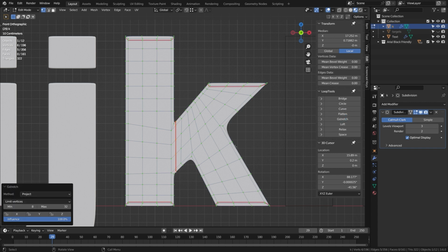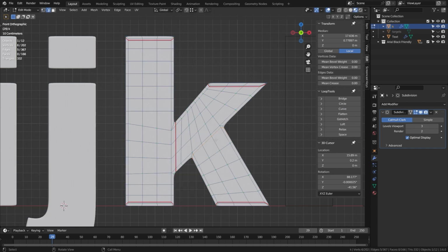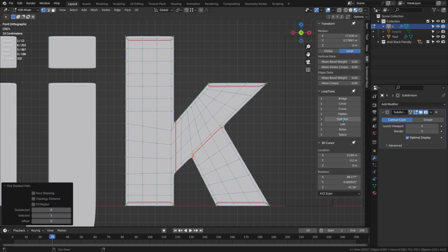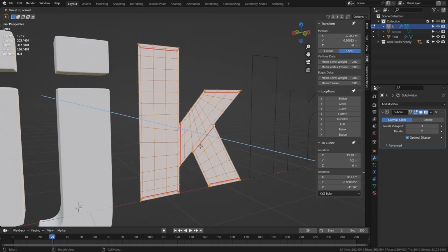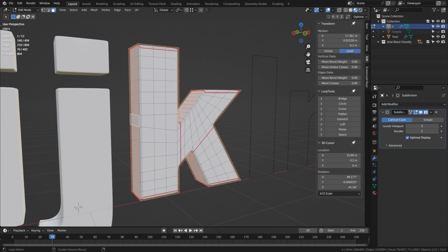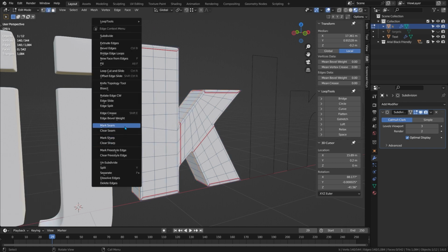And I'm going to do the same over here. This also connects to 2 internal corners. And I'll use G stretch on that as well. I'm going to move the camera a little, press A to select everything, E, 0.4, enter, 3, Alt and click, I, 0.04, W, and then mark seam.